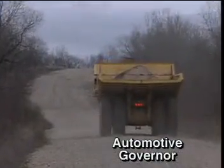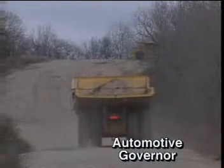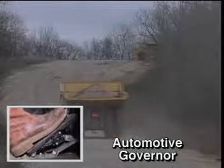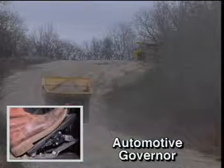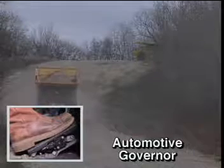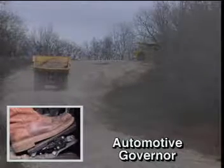With the automotive or min-max governor, engine speed between idle and maximum RPM is determined by the accelerator position sensor input, as well as by the load applied to the engine. Since the accelerator position determines the amount of available engine torque, engine speed is directly related to the amount of load placed on the engine. An automotive governor requires more operator interaction to maintain speed, providing improved feel.